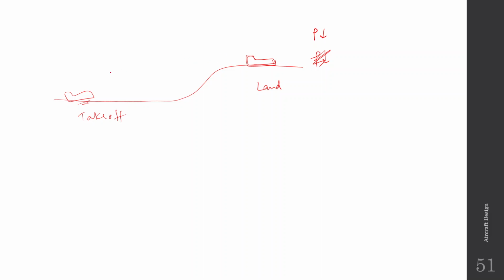So usually what happens is that the plane takes off from here, but then midway it has to communicate with ATC and reset its altimeter. So that when it is trying to land, the altimeter measures the local altitude, from this hilltop, and not from the sea level. So this is an interesting thing I wanted to share.